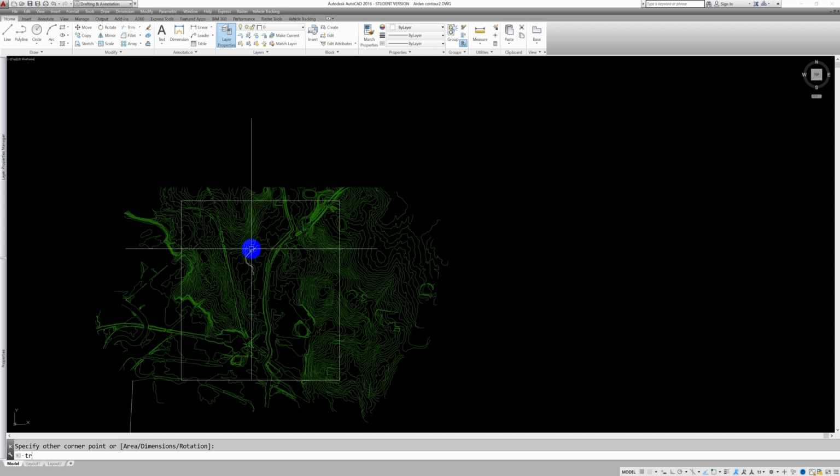The other thing I need to do is tidy up this contour line work before I take it into Max. It has a sort of a scruffy edge. Max really needs it to come in a tidy rectangle. If you need something that's going to accept a scruffy edge, you'll need to use CivilCAD. It's quite a good process as well.